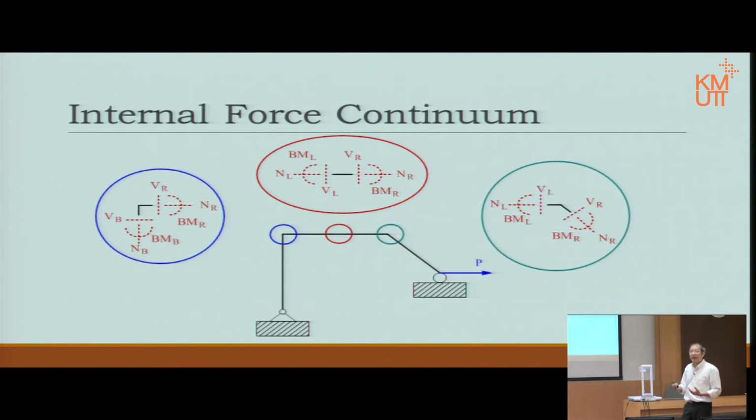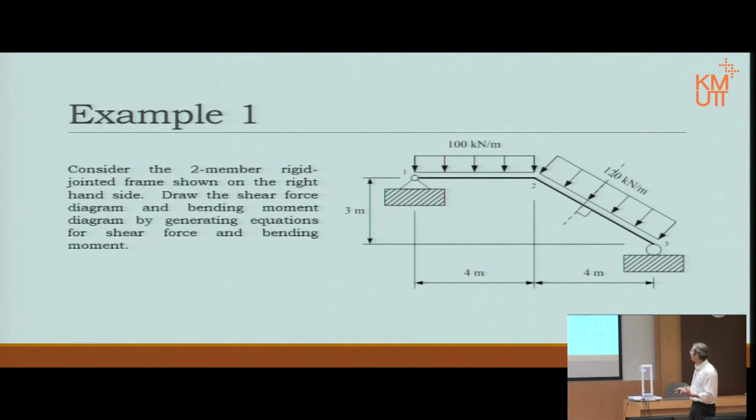Nevertheless, we have to understand that with this definition, which we're going to keep using, if it's broken down, it means that the section from the column to the section of the beam will no longer be considered the same equation for shear, no longer the same equation for bending moment. So we're going to change it according to the system. That is the only difference between what we have done before and the frame. Of course, the angle will make it a little bit more confusing, but still, the idea will be there.